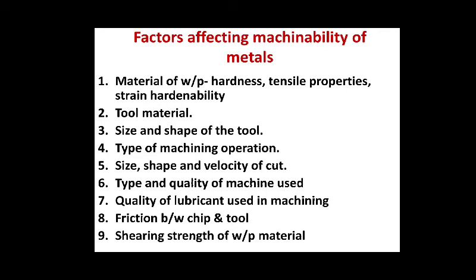Material of workpiece, hardness, tensile properties, strain hardenability, tool material, size and shape of the tool, type of machining operation, size, shape and velocity of cut, type and quality of machine used, quality of lubricant used in machining, friction between chip and tool, shearing strength of workpiece material.